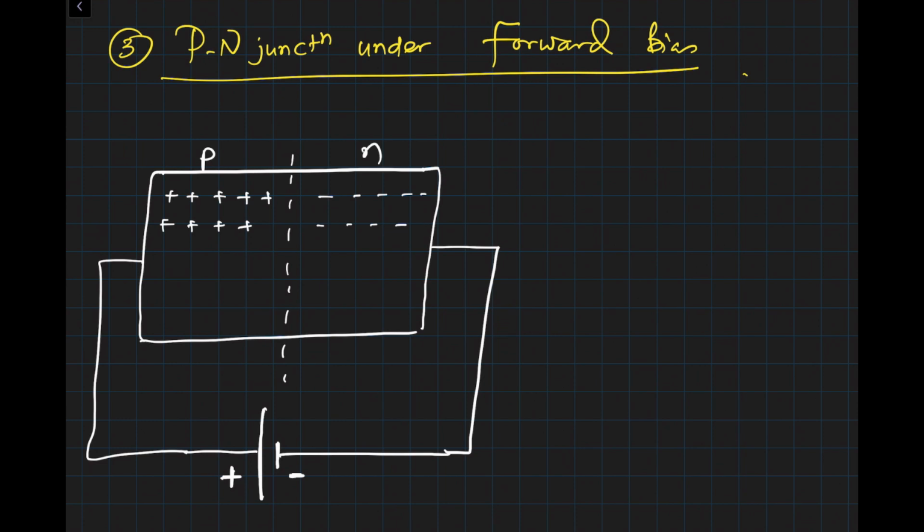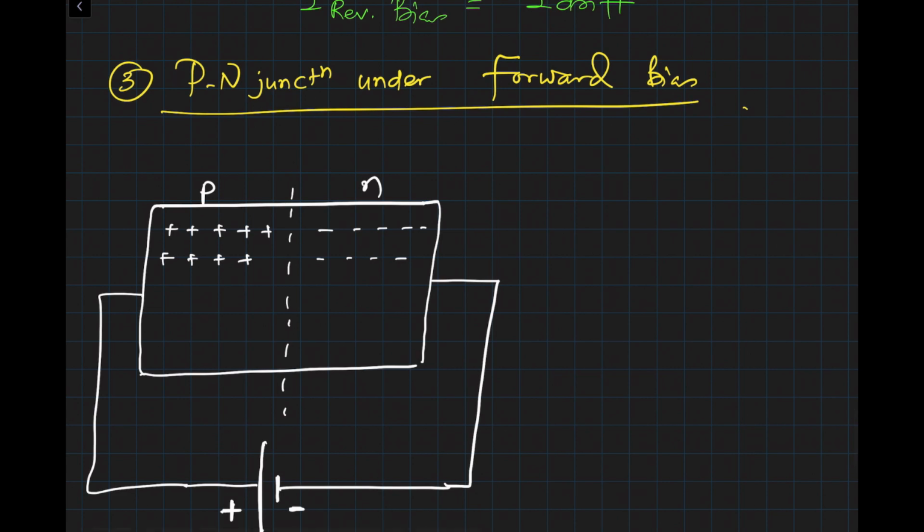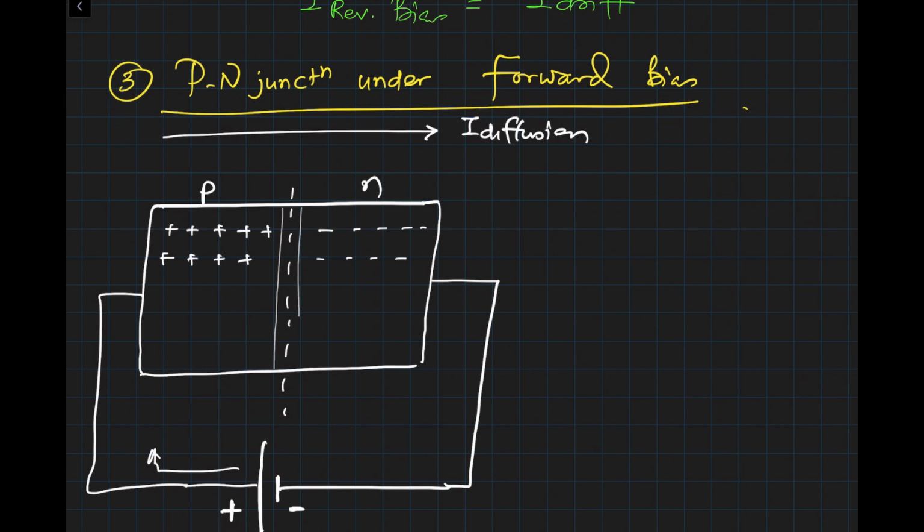So you will see there will be a large diffusion current. I'm going to show it here on the top. That should flow I diffusion from P to N. The holes will flow from P to N type, and then they'll get replenished again, flow this way. And as a result of which, you will see a current flow across the junction. The width of the depletion region will reduce substantially. So you will see really small region here which will have depletion region.